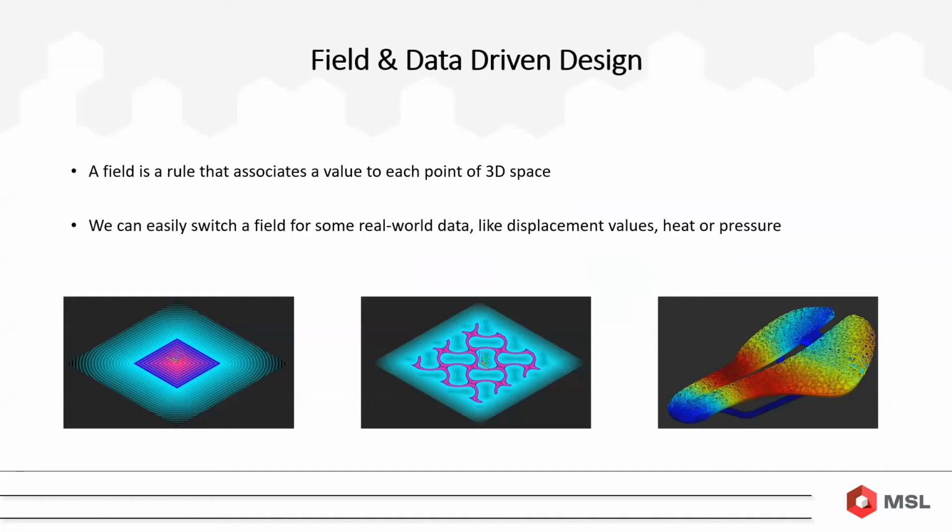I heard this described really nicely the other day in the context of a balloon analogy. If we take a look here, this is a section through a cube. Anything in this dark area is a negative value, anything outside is a positive value. So imagine blowing up a helium balloon in a room. If we imagine the helium is a negative value, the skin of the balloon is our boundary, and any of the free air in the room is a positive number.